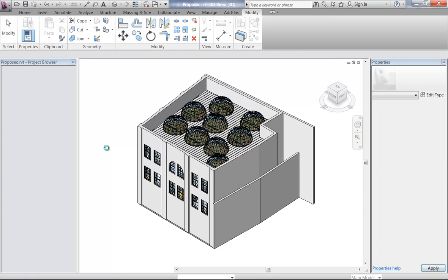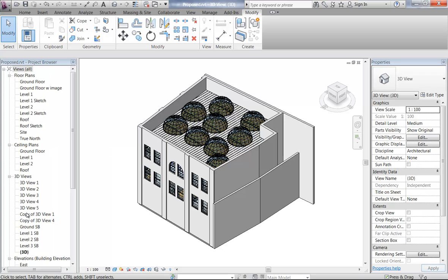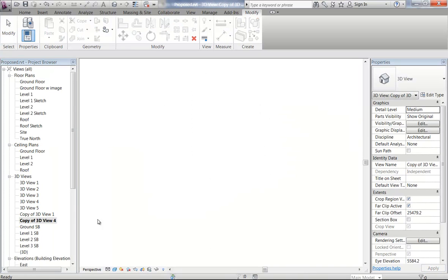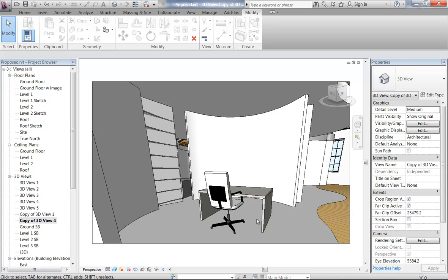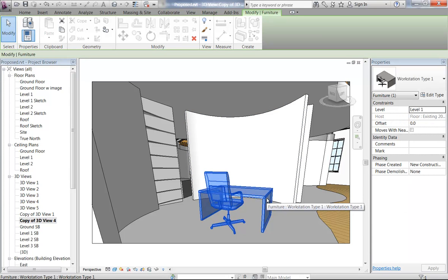Back into my perspective, and you can see it comes in with the chair, and that's much better than placing the chairs individually for each unit. You can have different configurations of chairs and just save them as different families, and it makes it much easier to manage. And then I can have lots of variations, so different sizes, and they'll all have the chair now.